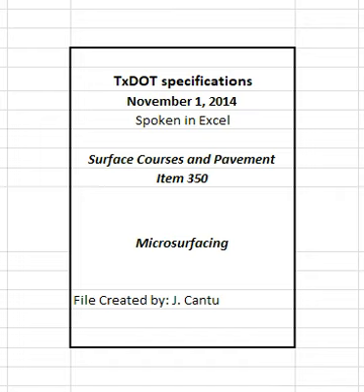4.5 Surface preparation. Prepare the surface by removing raised pavement markers and objectionable materials such as moisture, dirt, sand, leaves, and other loose impediments from the surface before placing mixture. Provide a water spray immediately ahead of the spreader box when required for existing surface conditions when tack coat is not required. Apply water at a rate that will dampen the entire surface without any free-flowing water ahead of the spreader box.